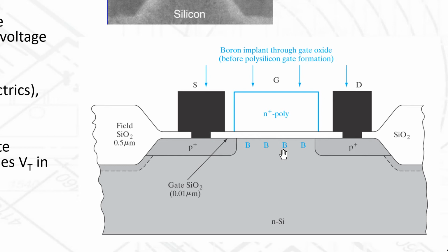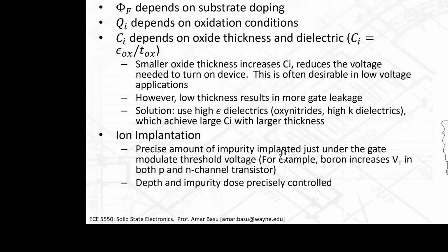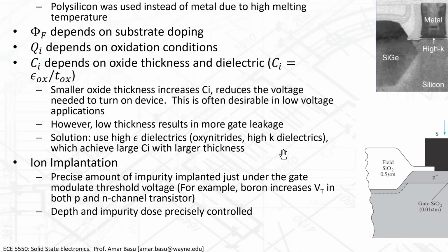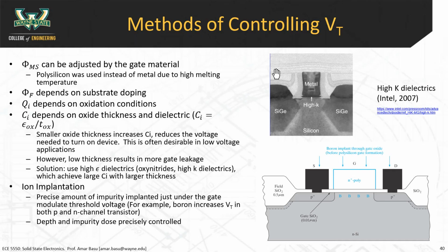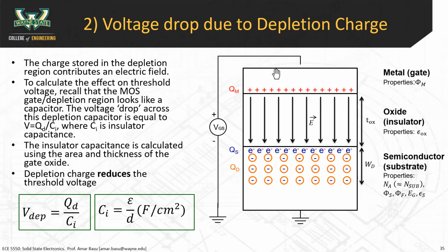So the intuition here is that the thinner the gate, the better the gate voltage can control the channel underneath the gate. Okay? And the mathematical way of thinking about it is like this. You reduce the oxide thickness, that increases the capacitance. Right? You're reducing Tox, so that increases the capacitance CI. And then the CI, if we go back to the threshold voltage equation,